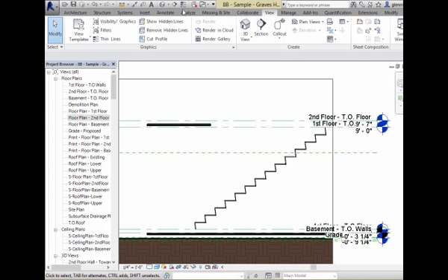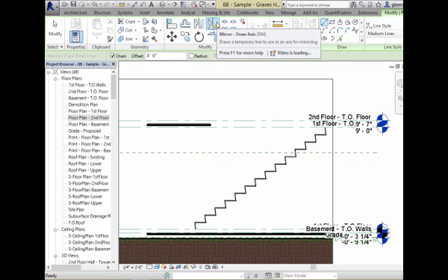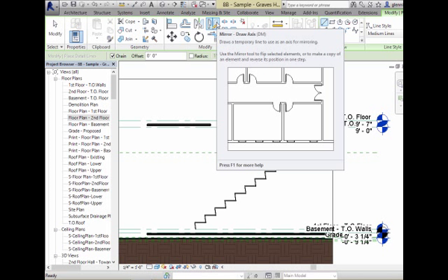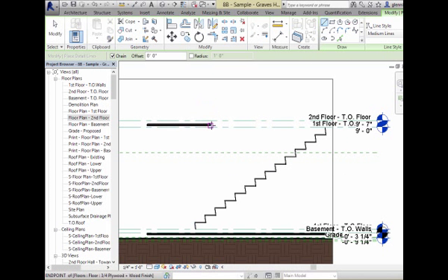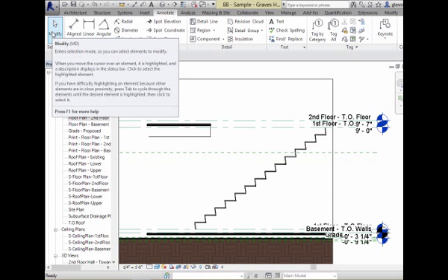If I don't have the structure modeled in there yet, a lot of times as I'm working, I'll just add little detail lines in there. Now, detail lines don't have any real physical meaning. It's just something to help me as a construction line understand what's going on. So I'm going to guess there's going to be about a foot worth of floor framing under here, and just draw that, just so I have some sort of sense. That has no real model meaning. That's just a little sketch for me right now.